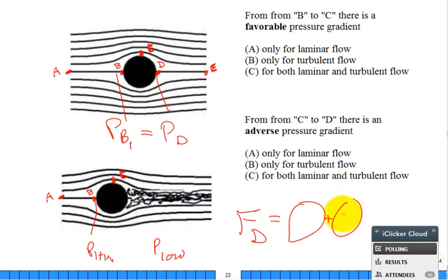It's the viscous, due to the viscosity, especially on the front half, and then it's the pressure, or form drag, all fluid mechanics, right? And that form drag dominates at high Reynolds number. And the viscous only dominates at Stokes flow or creeping flow.